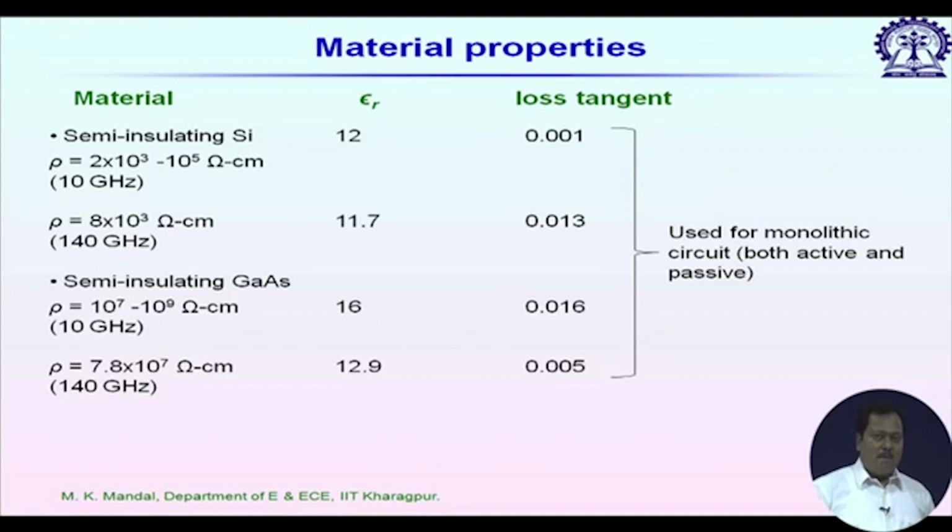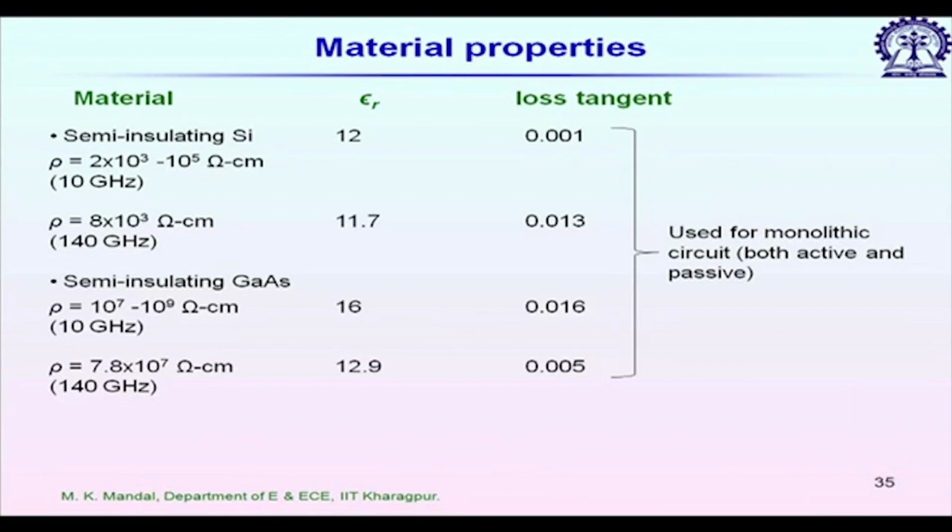So, first of all, silicon or germanium, and typically when we consider N type or P type materials, it is a semiconductor material. So, it comes with a finite sigma value. So, it is very lossy. So, we can't use these semiconductor materials as metal, or even as dielectric, because if we treat the semiconductor material as dielectric, it will be very lossy. Already at millimeter wave frequencies, we have many sources of loss. We do not want to increase the loss further.